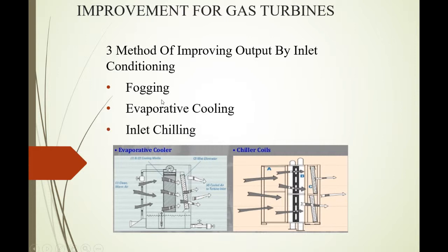Inlet chilling the inlet air stream is an effective way to increase the air density and thus improve turbine output. The chiller is typically a large mechanical refrigeration unit, which is adjusted to provide a controlled inlet air temperature to the compressor. No matter what the ambient air temperatures are, the chillers ensure that the compressor inlet temperature will not exceed a specific target temperature.